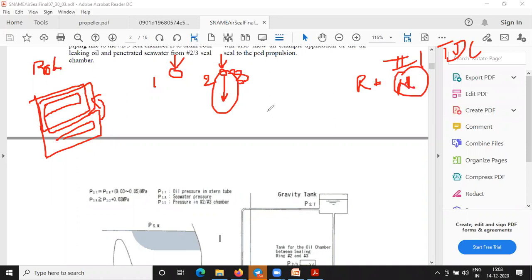So to take it at the same particular point, when you drop the poker gauge, it is going and touching where I said? The stern tube chrome liner. Now it was touching at the same point on the chrome liner. The next time also, when you take number one unit at TDC and in between the 2 and 3, you drop the poker gauge, it will touch the same point. That means you know that the earlier reading was also taken at the same point, and the new reading you are taking is also at the same point.